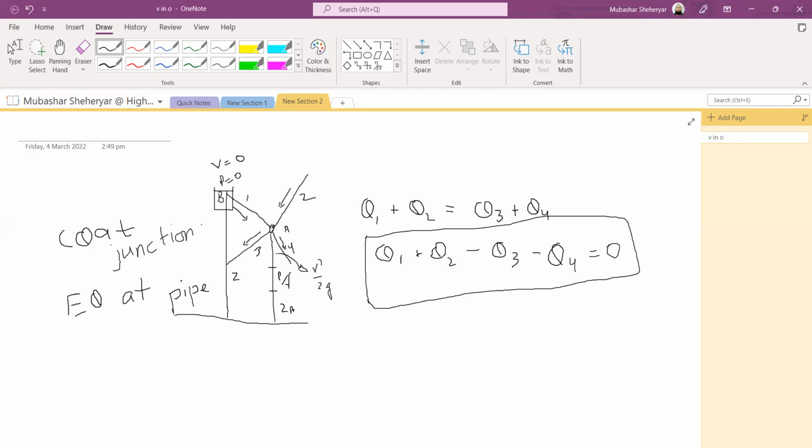To satisfy the energy equation for a pipe, it is necessary to assume a direction of flow. The water is flowing from B to A. Therefore, the energy equation for pipe A will be such that the head at B minus the head at A minus the head loss occurring through the pipe is equal to 0.